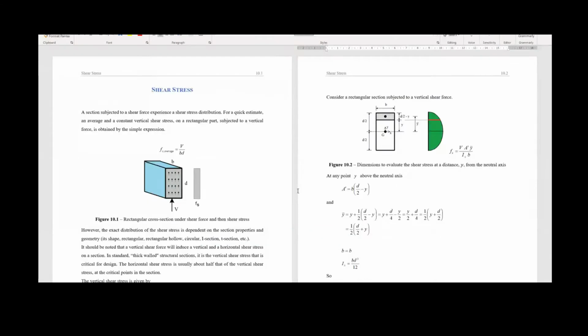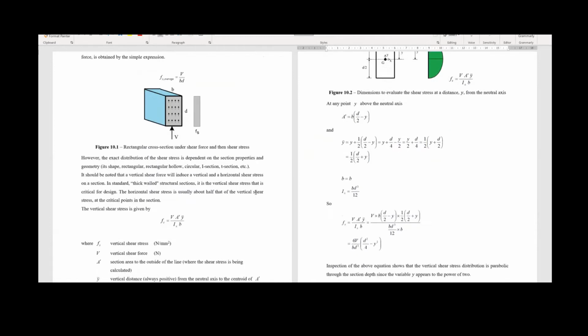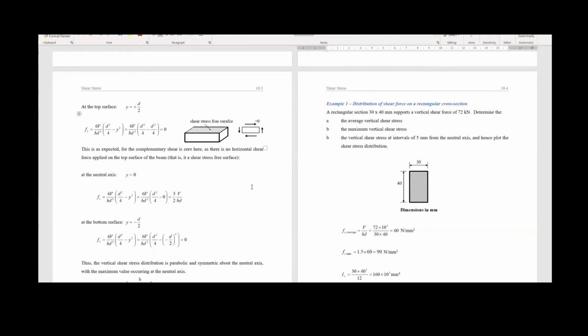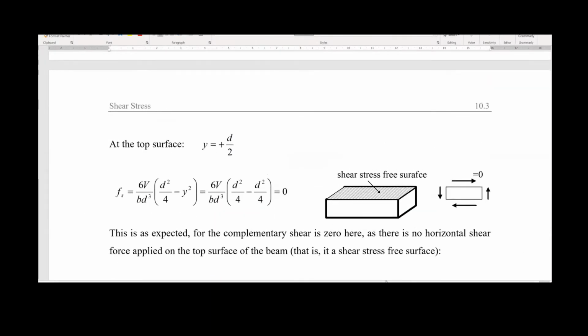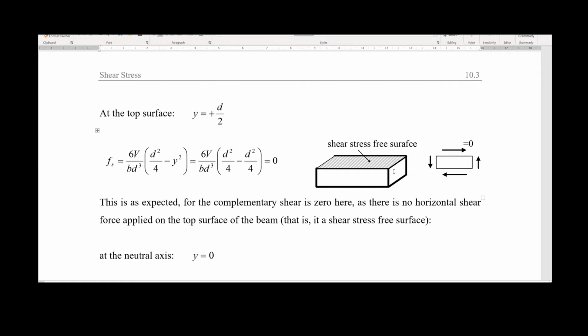Okay. If you ask yourself why the distribution of these shear stresses is parabolic and not linear, or why we cannot use this rectangular, uniform distribution in here, it is because, if you remember from previous lessons, and if not, you can check again, the way that the shear forces work is very particular. So the shear forces appear in a cross section, not only in the cross section itself, but in other sections that are perpendicular to the cross section you are analyzing.